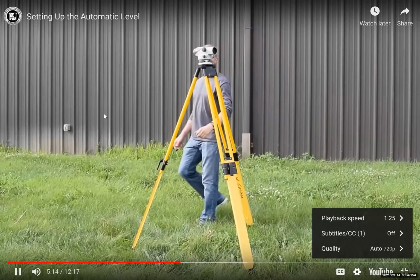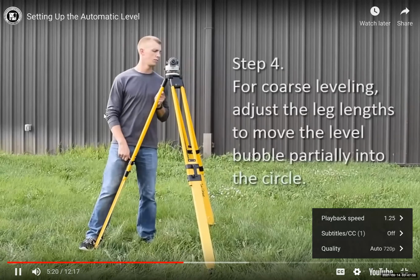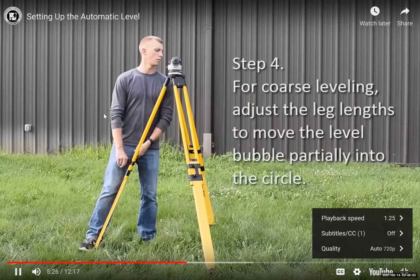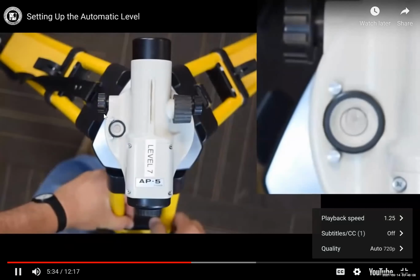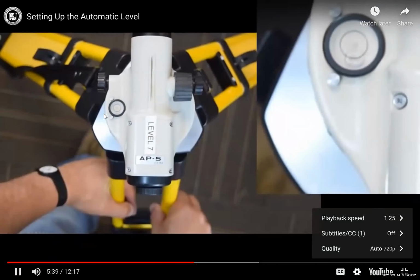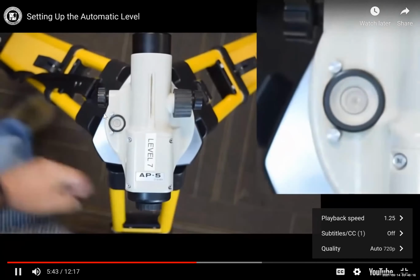While viewing the bubble level, adjust the leg lengths to move the level bubble partly into the circle. First, watch how a centered bubble moves when the tripod leg length changes. When I shorten the leg under the eyepiece here, you see the bubble move away from that leg. When I extend that same leg, the bubble moves toward that leg.